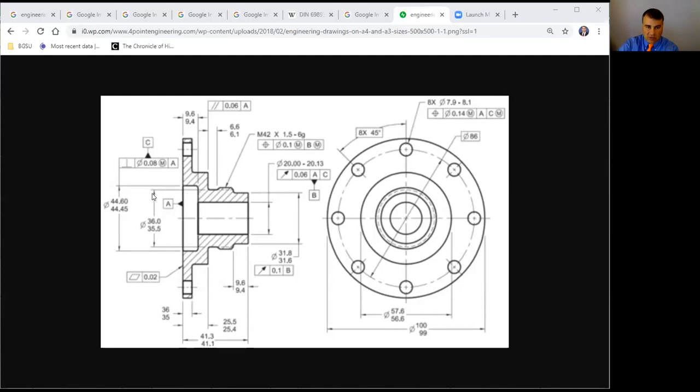Something that matters more because something's maybe nested in it or it's a contact surface will have a tighter tolerance. So for instance, this dimension in here, from here to here, probably has something sitting inside of it. So you notice its tolerance is only 0.15, the difference between 44.60 and 44.45.